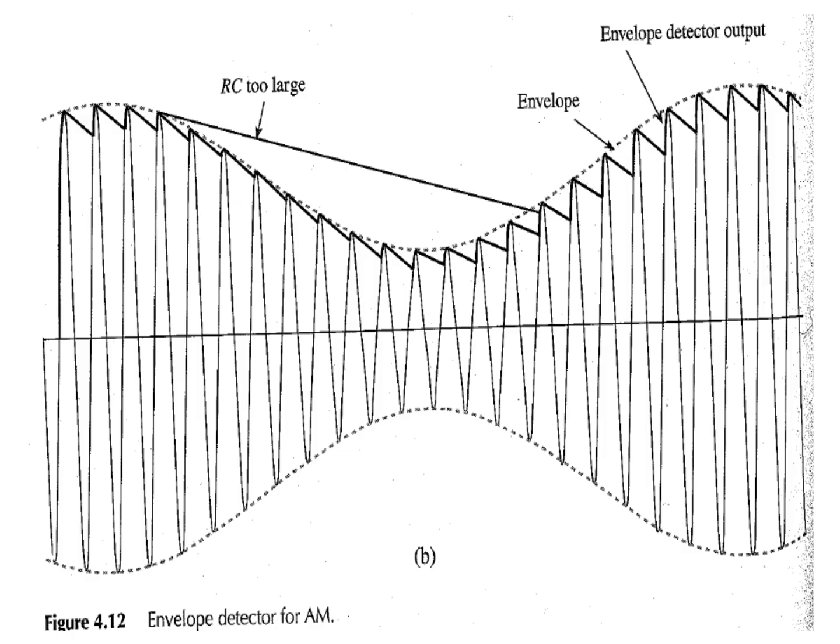Now let us look at the envelope detector. As you can observe, this is the discharging time and this is the charging time. As we discussed, the time taken to charge is very small and the time taken to discharge is very large. When it is discharged, immediately the next peak comes here, so again it is charged. Because the time taken to discharge is slow,